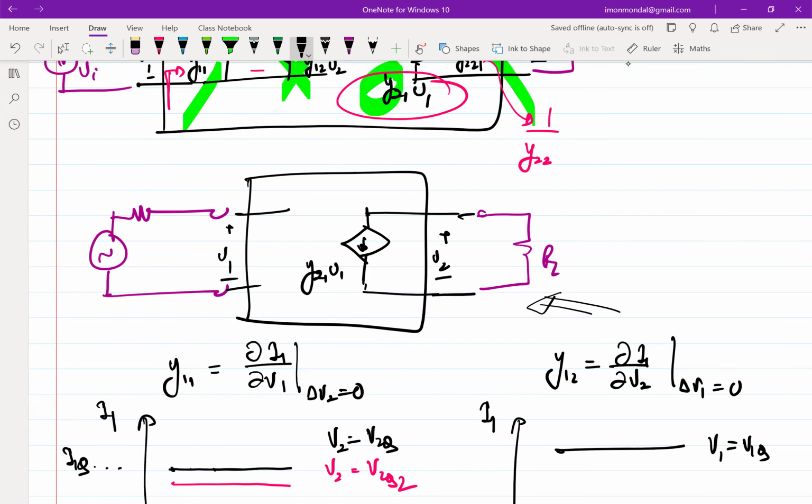So his point is it is an approximate network. That is true, but there is a deeper meaning to it. When I said that you cannot get power amplification using an LTI network, that is not a full statement. The full statement should have been: using the devices that we already know of, that is using RLCs, or even any other linear device that might exist.